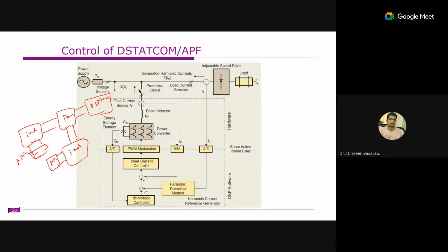If the load that we are compensating is in the same vicinity, that is usually known as an active power filter. If it is installed directly at the distribution network or distribution station itself, that is usually known as a D-STATCOM. But it doesn't matter whether it is compensating their own loads or their combined loads, the control remains the same. So these two words can be used interchangeably.